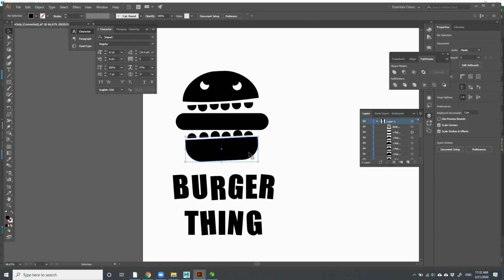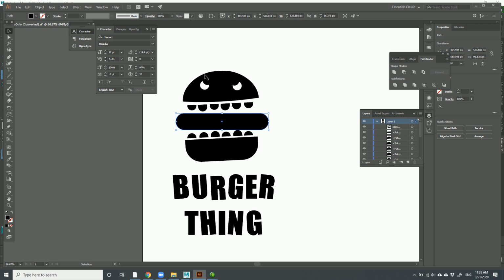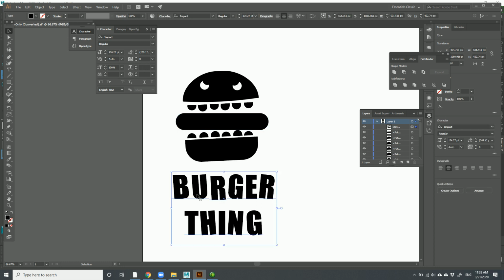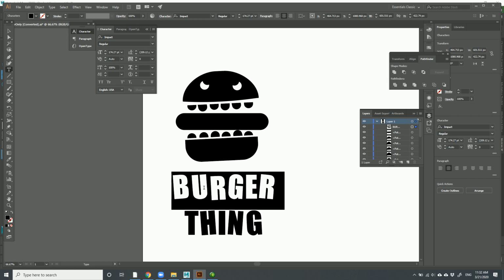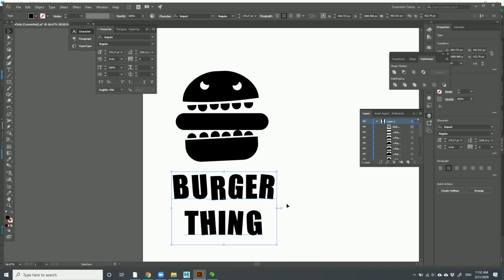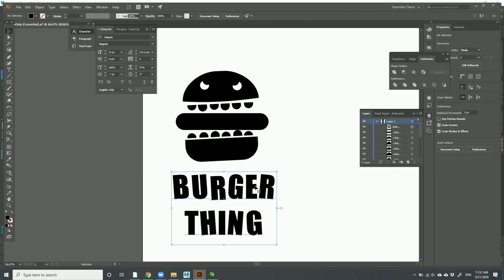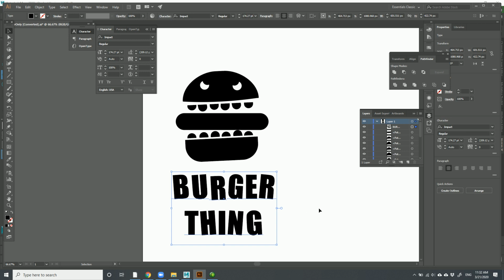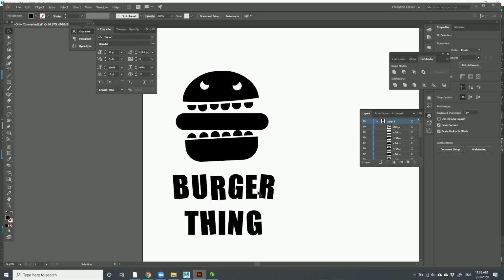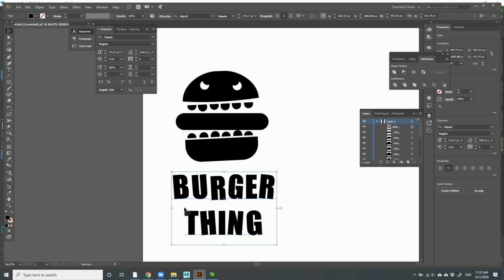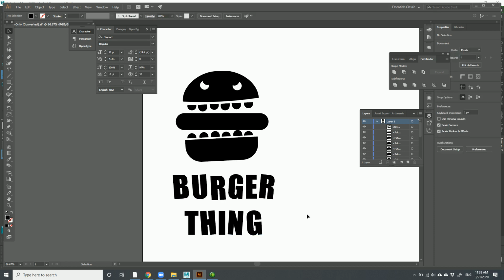Okay. So this is a vector, but this is still a font. And if I wanted to go in here and type in something else, I still can. That's editable text here. So what I'm going to do here is convert this. This is very important because Maya will not accept this sort of stuff. It needs to be vectors here. Maya is not a vector program, just as Illustrator isn't a 3D program. So I need to convert it into the bare basics sort of format here.